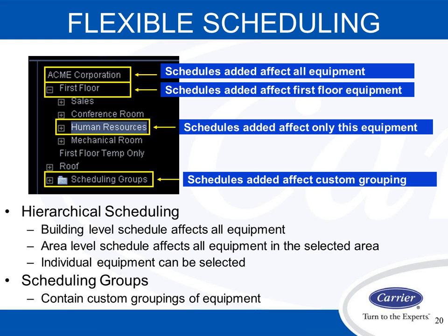Or if you put it in the scheduling group, you'd actually select what room you would like. So if you wanted one from, let's say, the roof level, which I would assume would be like a rooftop, and then maybe one of these zones if the first floor was like a zoning system, you could select that so it has the same scheduling group. Or you could specifically go into each controller and put its own schedule in there.